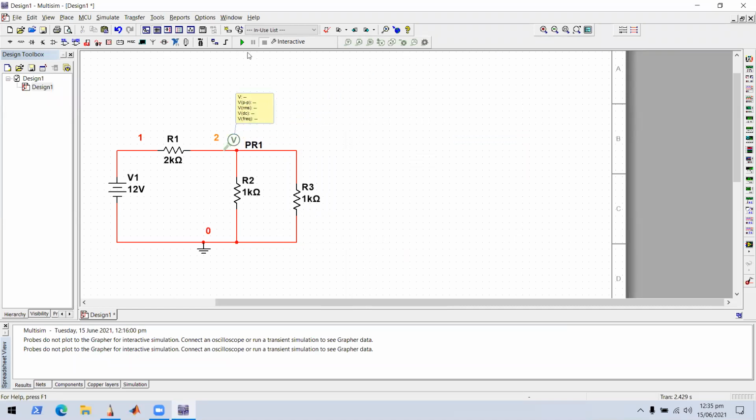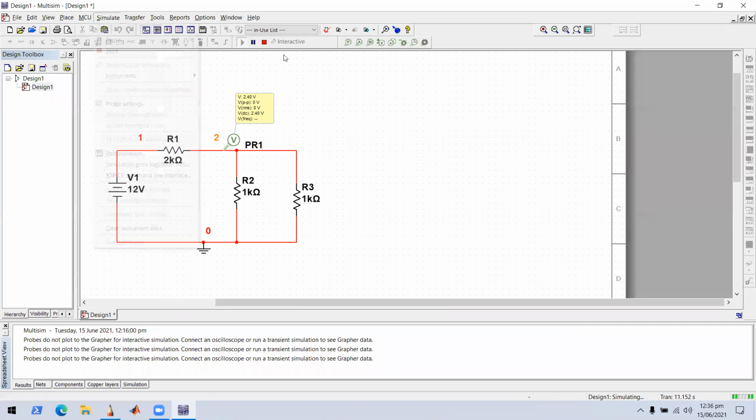And what this does, when we simulate the circuit, it'll display that voltage there, right? So maybe you don't want to work so hard and go collect a multimeter and connect it up, or go into your components and find a voltmeter and connect it up, right? You just want a quick probe. So you can use probes, and that picks up certain things like the voltage, right? And it can specify whether that's AC or DC voltage.